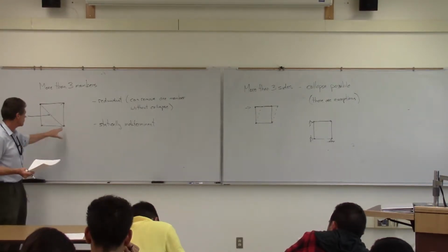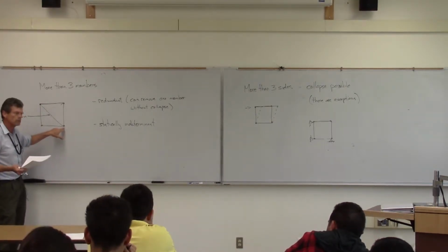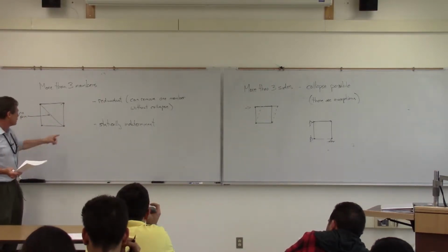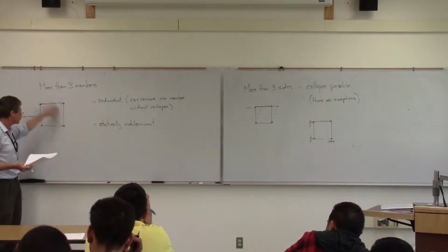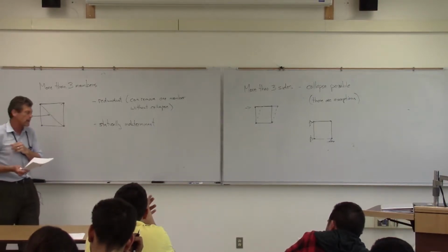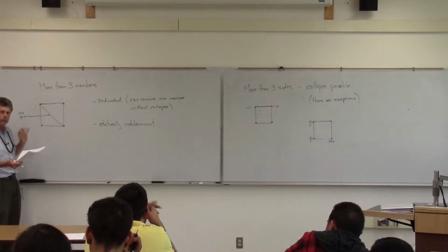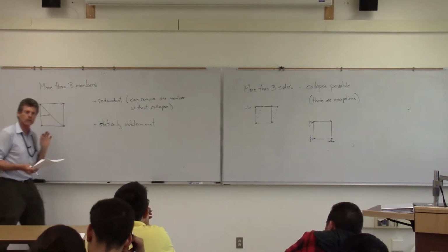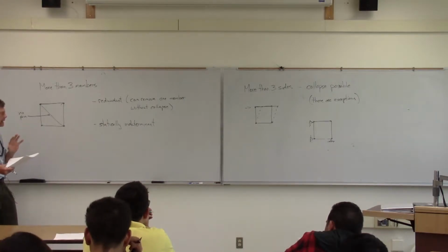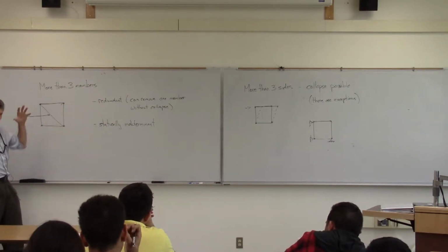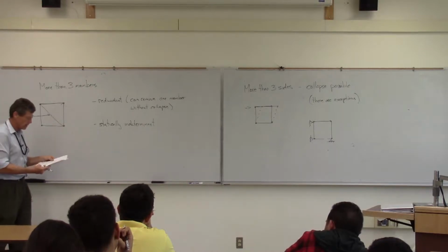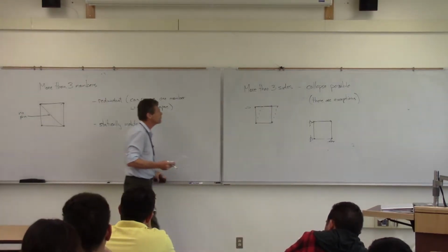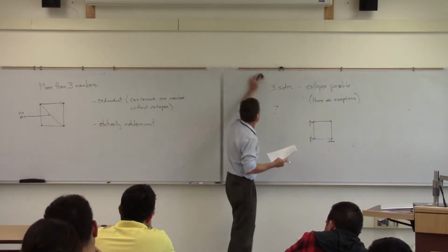They had a situation where all the gusset plates were actually designed a little bit smaller than they were supposed to be, half the size. And finally, one of them got tired and gave up the ghost, and then the whole structure came down. So that's why we tend to like redundant structures. Because if there are issues with a member getting overstressed, or breaking, fracturing, or something like that, we can see it, the rest of the structure is holding up, and we can then maneuver to get it fixed, get people off of it, for one thing.